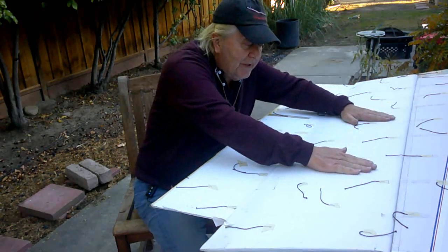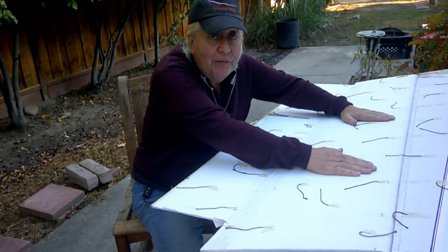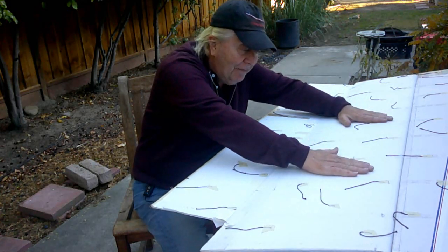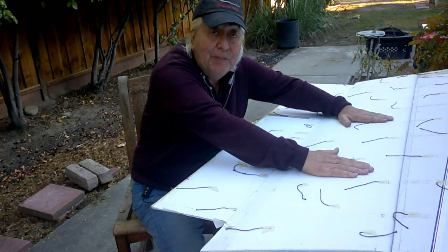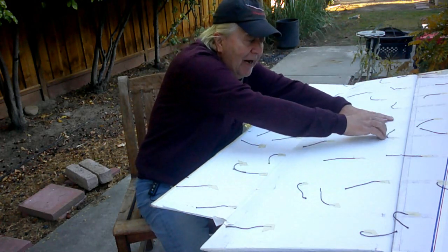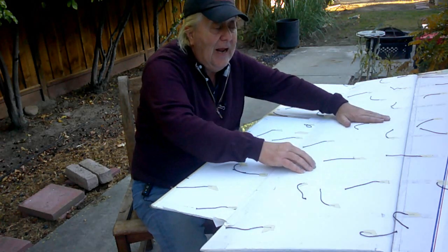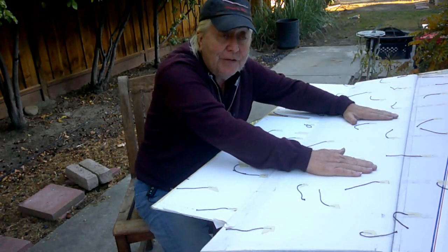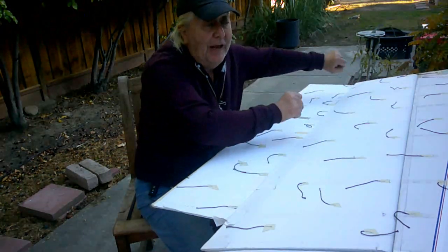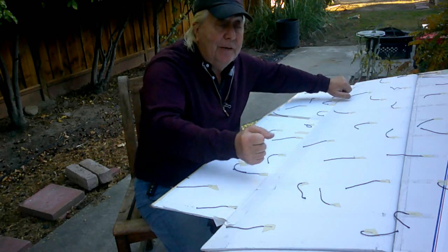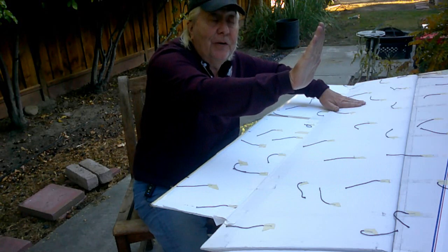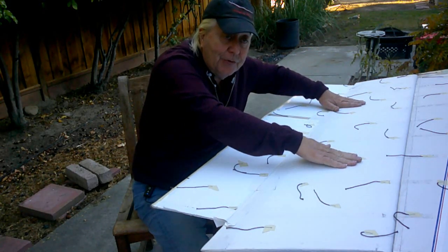The problem with spoilers is they're always spoilers. Even when they're closed, they're spoiling the flow. Those spoilers sit on top of the fabric. They stick up about 3 millimeters. They're stitching in fabric in front of them, and they're only held down by aerodynamic forces. When you move the A-frame, it pulls on a cable that pulls on a system, and a little lever comes up and pushes the spoiler up. But aerodynamic forces push it back down.